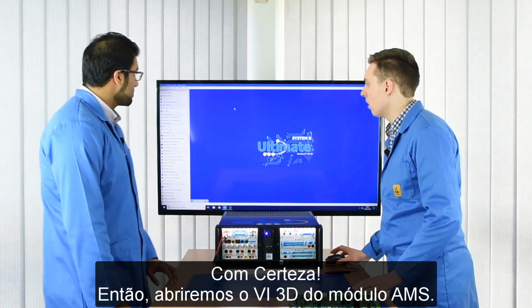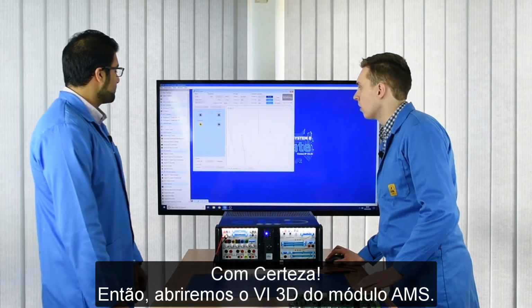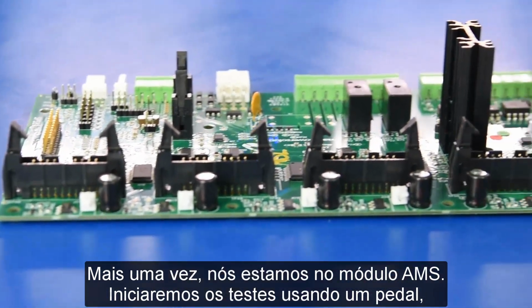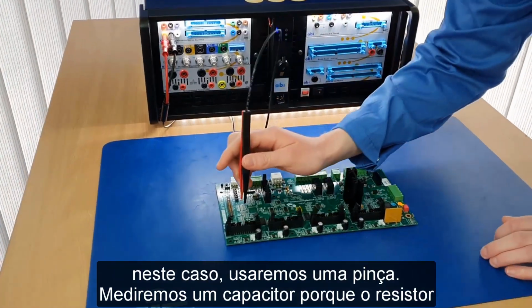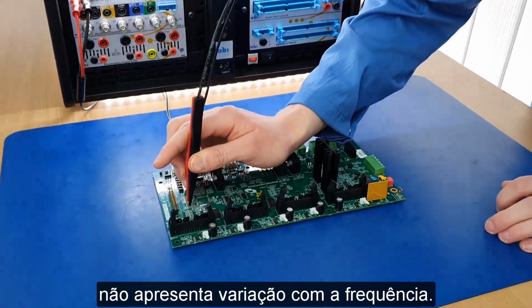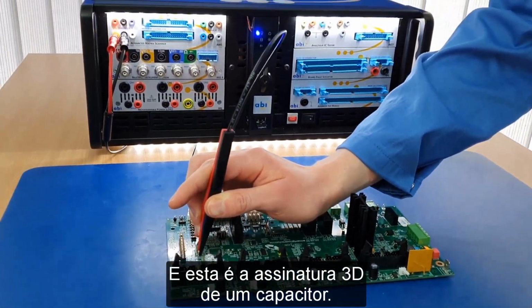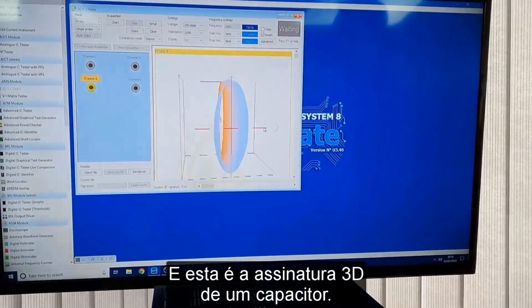Absolutely, yeah. So I'll bring up the 3D VI in the AMS module. So once again, we're still on the AMS module. Start test using the foot switch. Okay, we're using the tweezers in this case. So I'll measure a capacitor because the resistor wouldn't show much variation in frequency. There we go, I can stop the test. And that's our 3D model of a capacitor's VI signature.